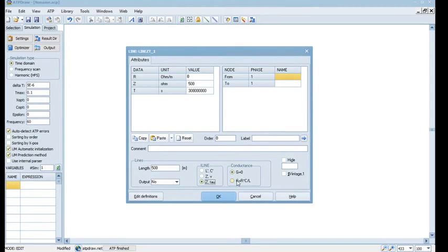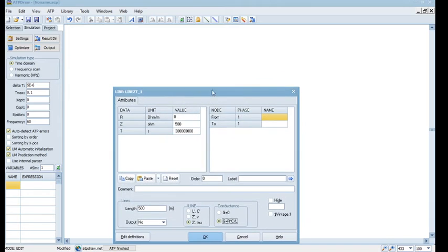And if you want conductance, G, to be included in this simplified model, you can include that, proportional to some constant values. Just note, if you make G 0 and attach R externally to this Bergeron model, fine. Bergeron model is an exact model for a lossless transmission line. Just as a reminder, R actually gets attached as an external element. So you can experiment, in fact.